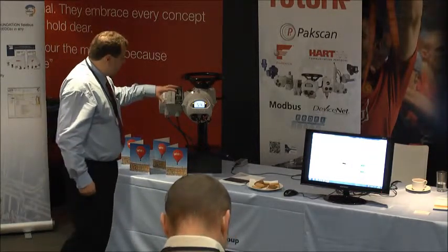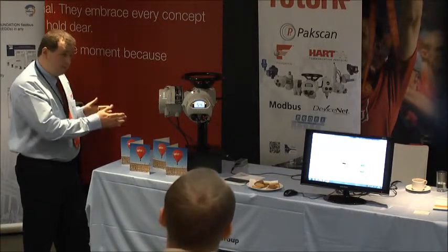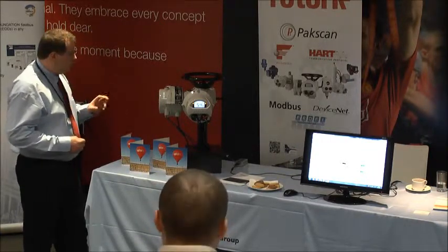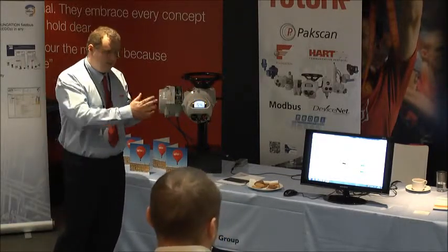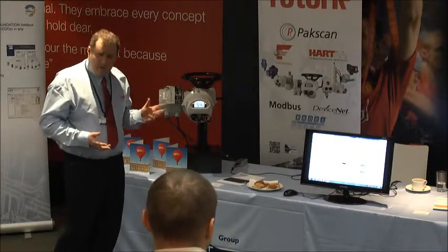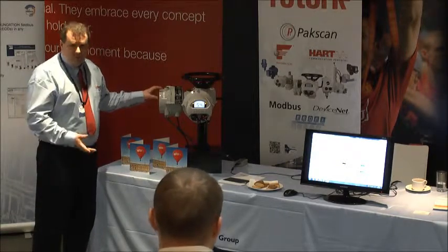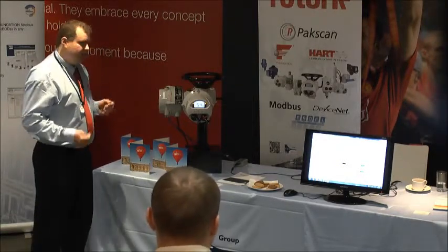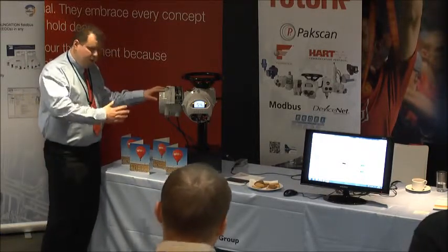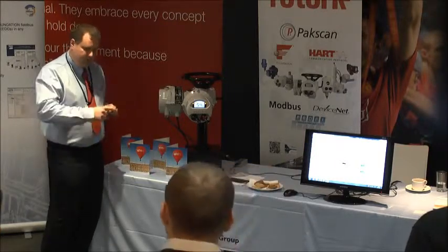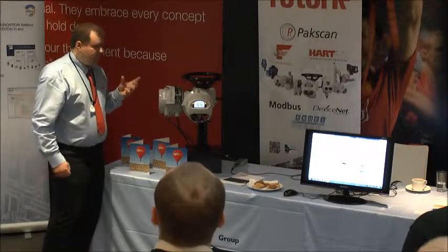And these actuators will also store the torque values seen at different percentage of their travel for open and closed. So rather than trying to have this open all the time, you can specifically go and monitor it and look at the full stroke if you want. But it may be that the process that's being run doesn't often demand a full open or full closed, and many sites run 24 hours a day, so you can't just do that. However, over its history, as it has moved open and closed, it will store torque at those particular points, and you can then read that back through an ATM, and that will show you sort of a history.